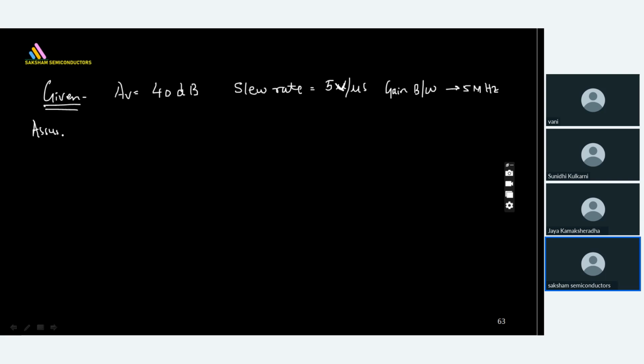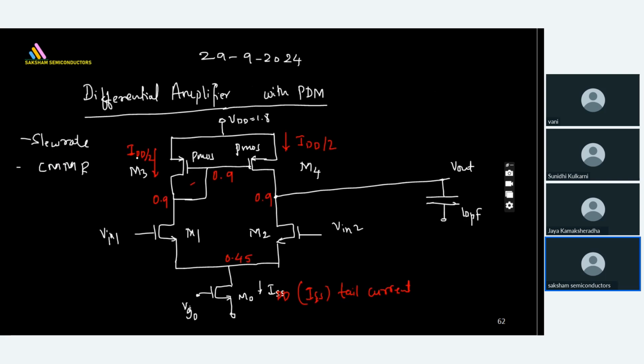When I try doing this, I'm going to assume L is equal to some 4 to 5 times the normal fix, which is my 500 nanometer. Also, if you see the previous things, let me mark this point as node Y, and let me mark this as point X, and this is your V out. So if you see here, Vx is equal to V out. Always remember that.